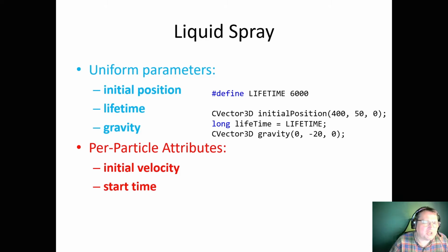It's just when I used -10, these droplets of water spray, of liquid spray, seemed too light. Okay, the gravity was not strong enough. With -20 we get a better result, and please note that the x coordinate is 0, z coordinate is 0, and the value of gravity is stored as the coordinate y.